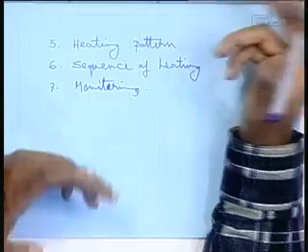Now, in this monitoring, again the same issues. When I am finding the heating pattern at the fifth step, now I have to bend a plate, that geometry is given. That heating pattern I should be able to generate online, immediately, not that I run the computer for 4 hours, 10 hours and then get a pattern of heating, because then the whole purpose is lost.